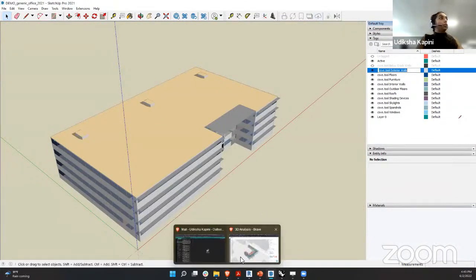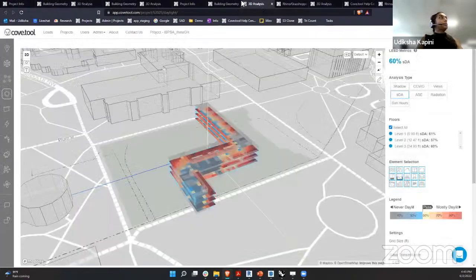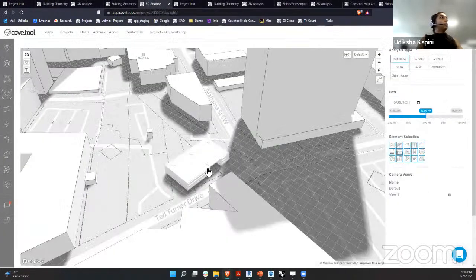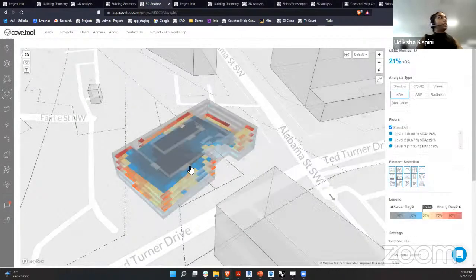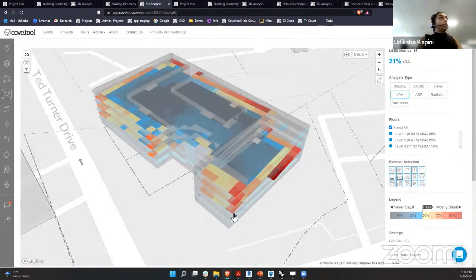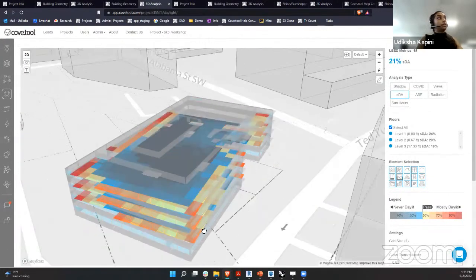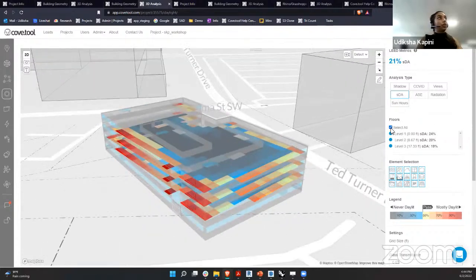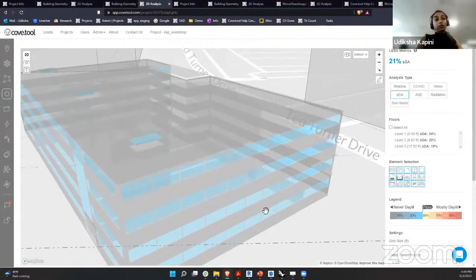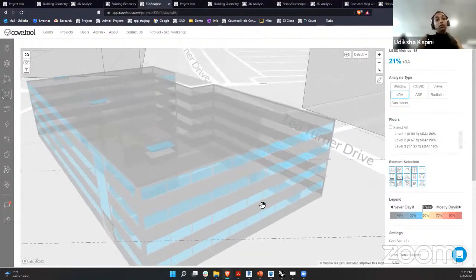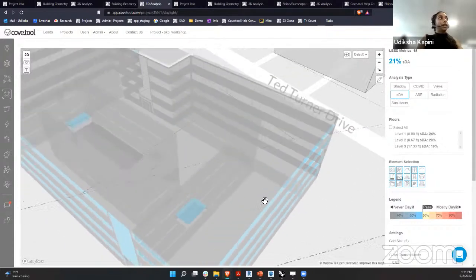And I'm also, again, going to show you this exact model on our platform. Okay, opened up the wrong one. So yeah, right here, this is the model that I exported from SketchUp. And like I said earlier, we do need single surfaces since SketchUp is not a BIM tool. There is thickness involved if you have modeled it with thickness, but based on the rules that we can grab onto, we do need single surfaces for this export.